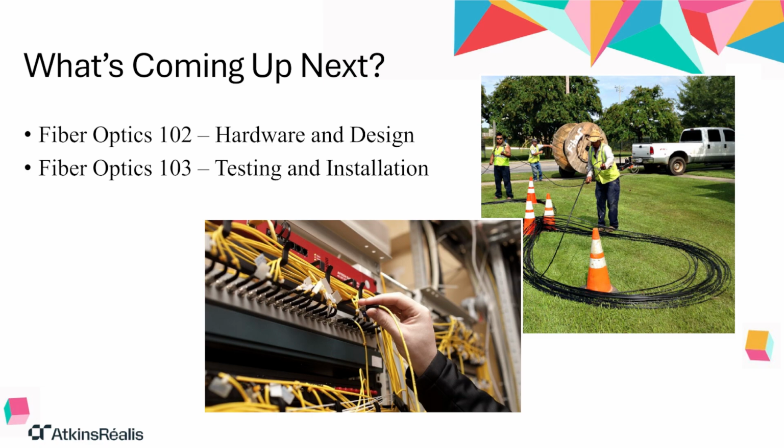Just to quickly recap for everyone listening, we hit our three main goals. We dug into how fiber optic technology works, those pulses of light representing zeros and ones, bouncing down the glass core via total internal reflection from source to destination. We explored why FDOT uses it, the huge advantages in speed, distance, bandwidth, reliability against interference, and security compared to copper. And we detailed what cabling is typically used, breaking down the components from the tiny fiber core, cladding and coating, up through buffer tubes with their color codes, and looking at different cable types like the loose tubes specified by FDOT, plus armored and aerial, and the crucial concept of minimum bend radius.